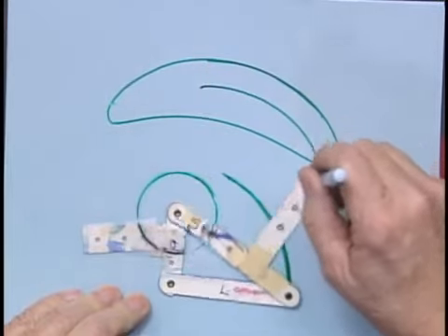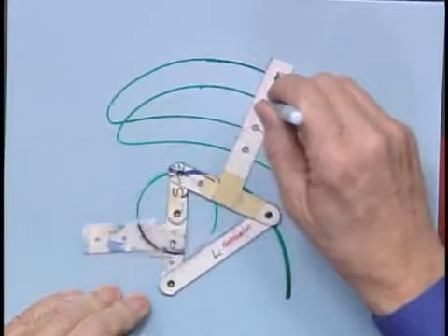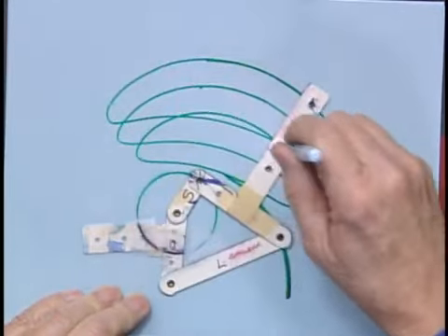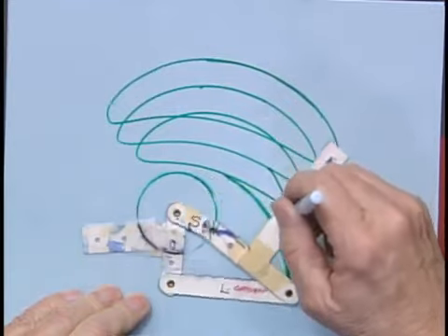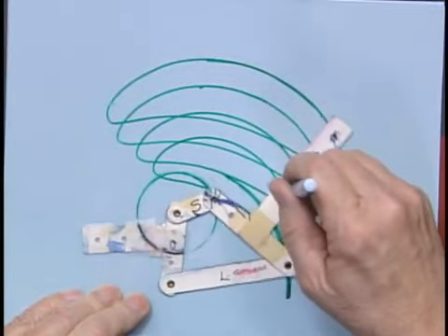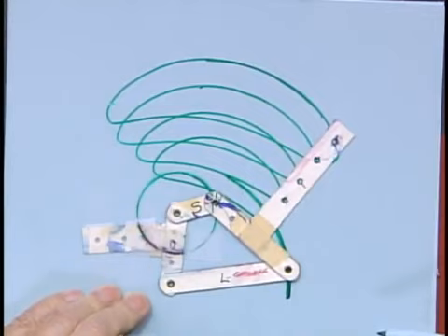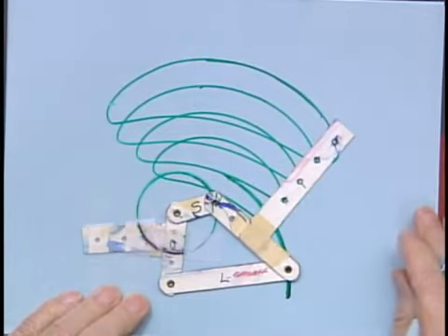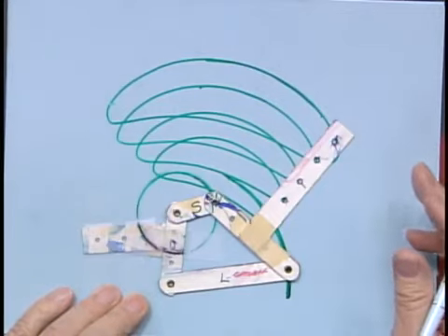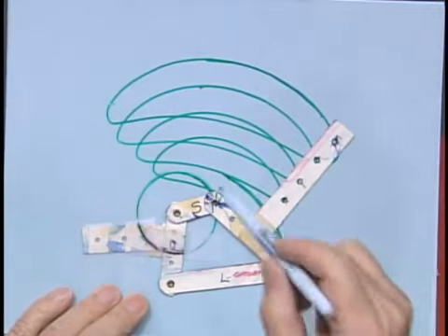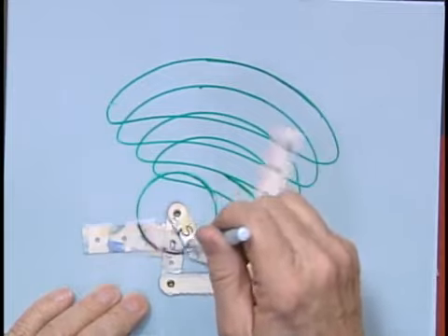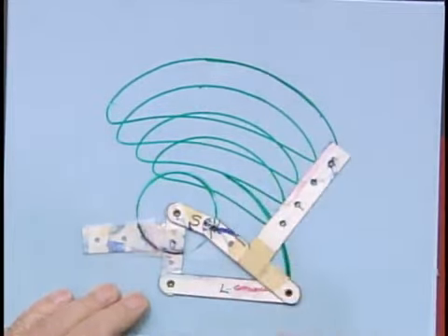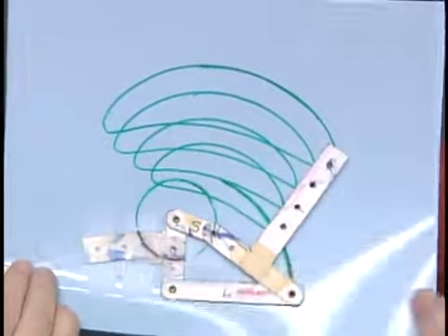These are going to be fairly similar to one another because they're so close together on the coupler. But I made the small coupler, as I said, so you could see the curves without too much interference. So there it gives you some sense of some variety of shapes that you can get. And you should not be surprised by the fact that given a Grashof linkage in which one link can make a full circle, these are closed curves. The coupler curves all close.